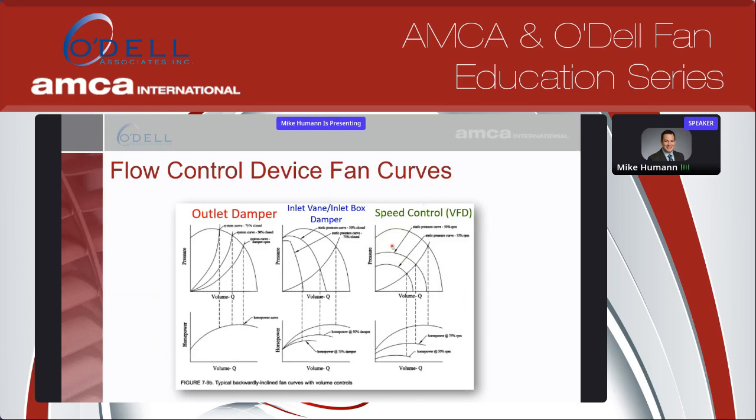The most versatile fan really is a fan that's on a VFD with an inlet vane damper when it comes to turn downs. You can really get a lot out of a fan, and where you may be in an unstable portion of the curve normally, if you add that combination of the inlet vane and the VFD, you really get a lot of flexibility in what you can do, and make sure you stay at a stable point on the curve, depending on your application.